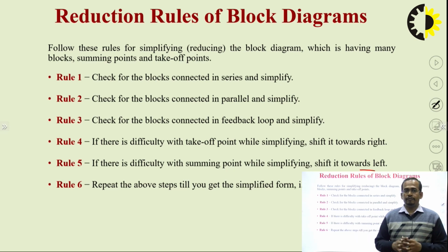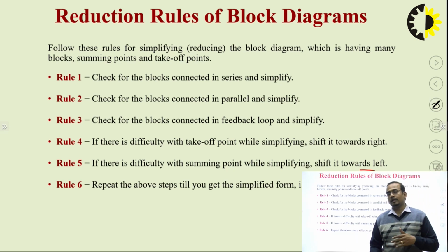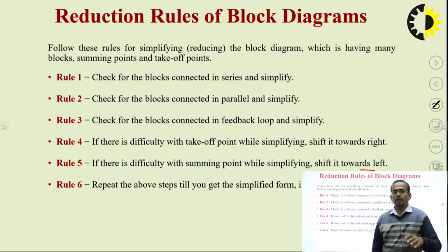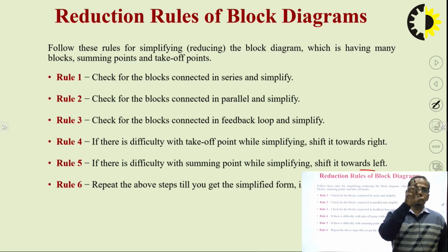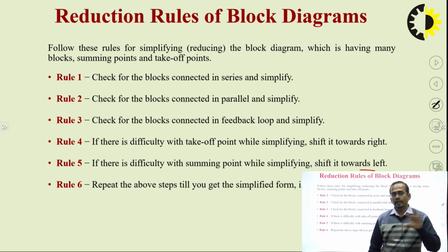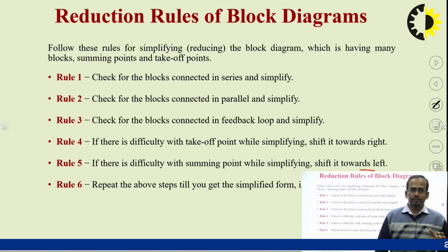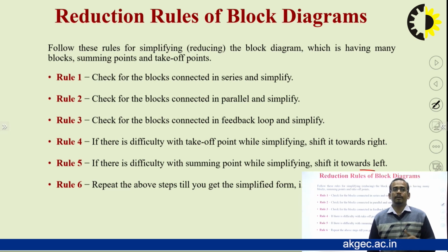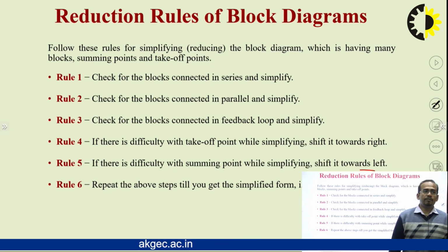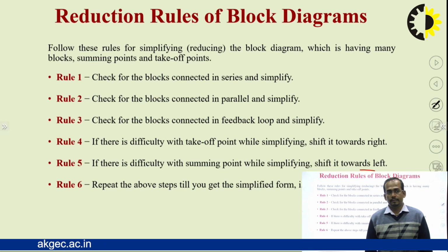The basic methodology for shifting the takeoff point right and the summing point left is that you are trying to convert the given block diagram into a standard canonical form. If you see the standard canonical form, the summing point is on the left side and the takeoff point is on the right side. So if you bring the takeoff point towards right and the summing point towards left, it will be very easy to simplify the given blocks and you will easily get the simplified expression of the block diagram.